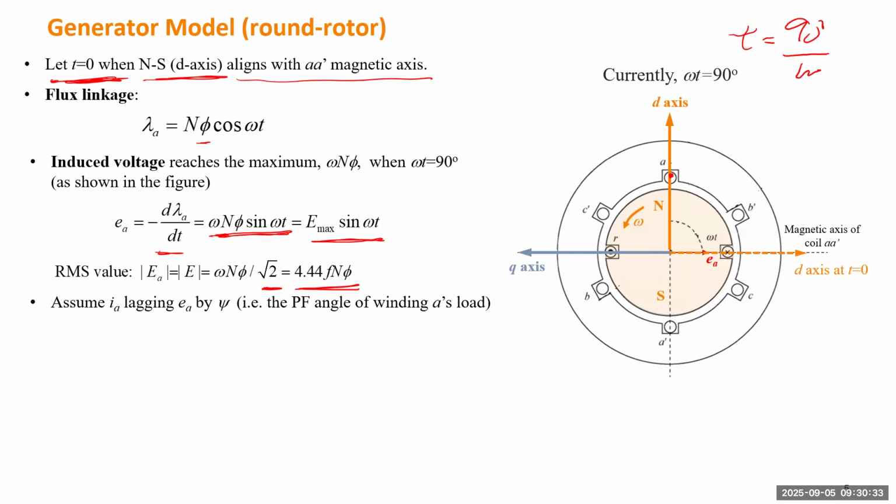Okay, next we want to determine the direction of the current. If we treat the generator as a source and everything else connected to winding A as a load, the entire load of this generator will have both active and reactive load, so it will have both P and Q. Which means the current in winding A will not be in the same direction as the voltage in most normal conditions.